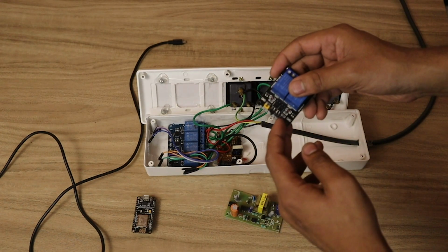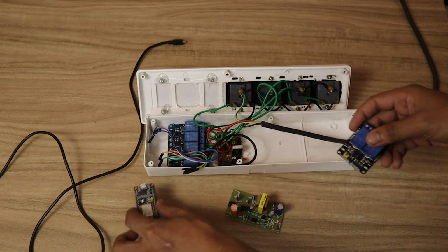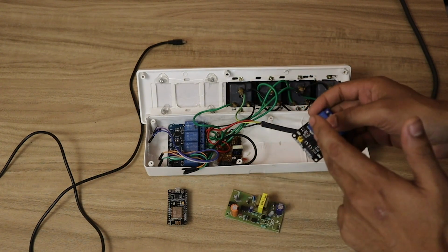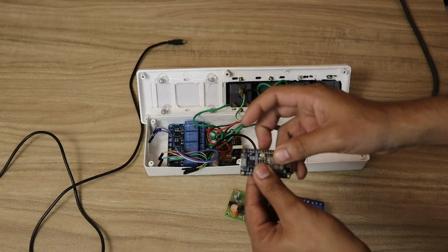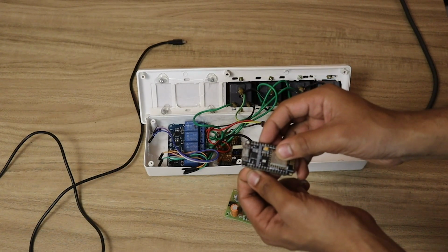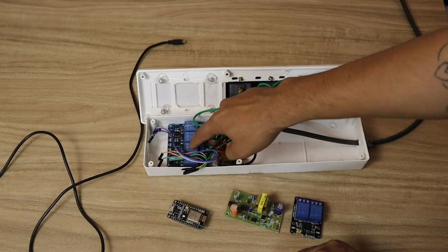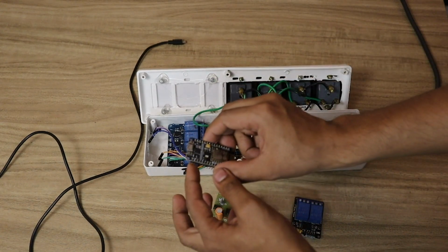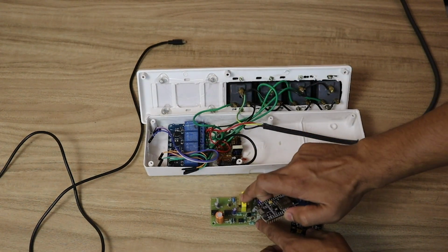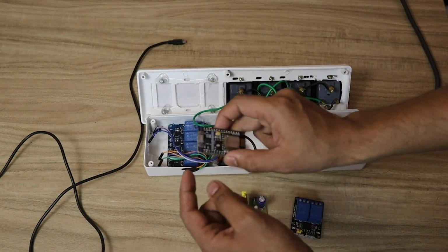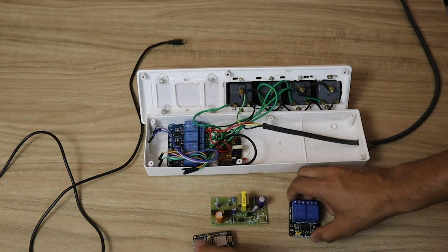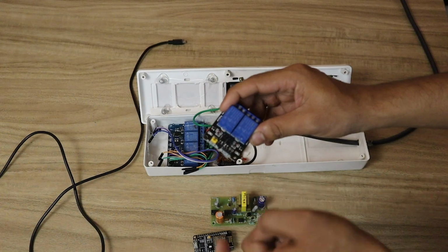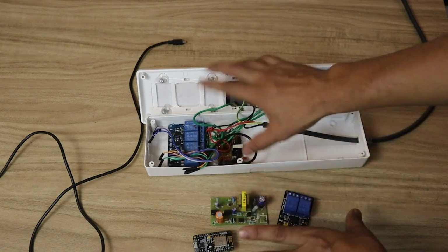Also here we will have the digital input pins, so you connect the NodeMCU with the input pins so that the NodeMCU can control the relay. In our case we have already defined D0, D1, D2 and SD3. These 4 pins I'm going to connect with the relay. I am also going to connect the VIN pin of the NodeMCU with the 5 volts I'm going to get from this, and the ground to the ground pin of the NodeMCU. Similarly, I'm going to connect a 5 volt pin to the VCC pin of the relay and a ground to the ground pin of the relay. This is how overall the connection will be.